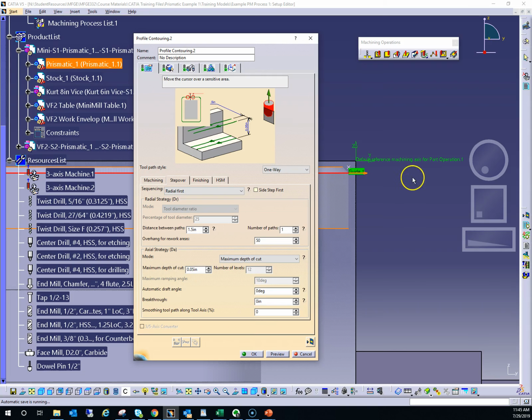This is the radial direction. So we have to increment in, we have to move in one pass at a time. Also too, we have to drop down in depth. And again, if we had a huge chunk of material out here, it would not be possible for the cutter to be at full depth, depending on the radial thickness at the same time too. So one has to look at both the radial engagement and the axial engagement simultaneously. So one has two directions that one moves in, radially and then axially. And the sequencing that one follows depends on which one does first.